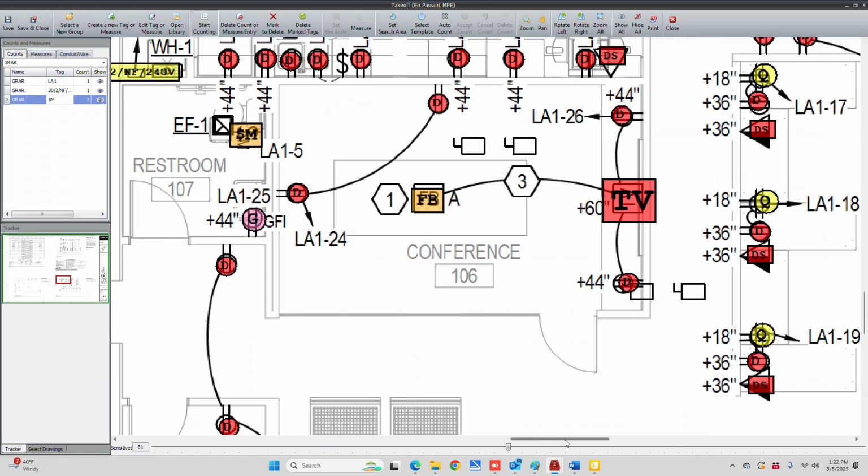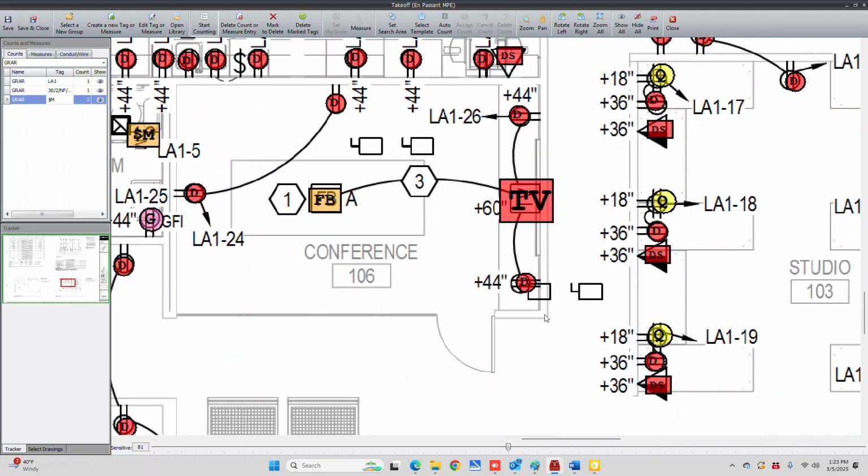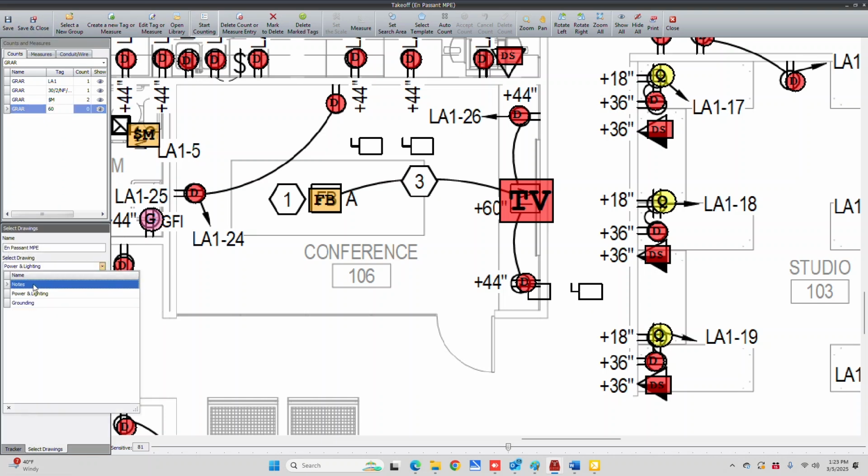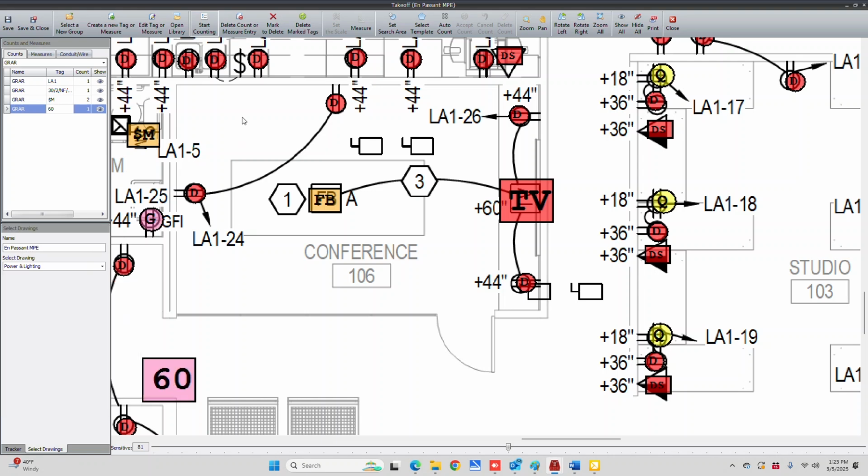Now I see in the background the 4 disconnects. They were for the rooftop unit 1 and 2 and the heater 1 and 2. And they were both 60 amp. I do not remember if it was single phase or 3-phase, so it's better to check. Actually, it's on this page. Remove that mistake I made.